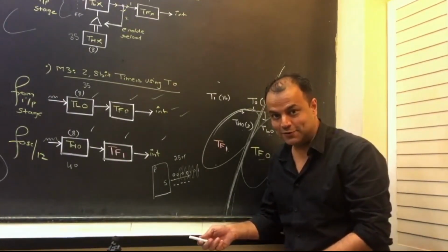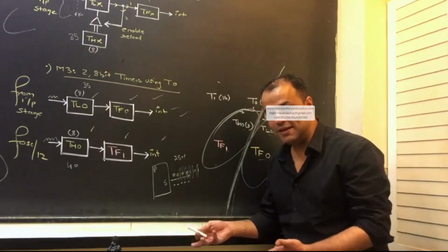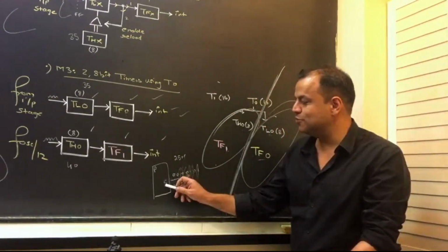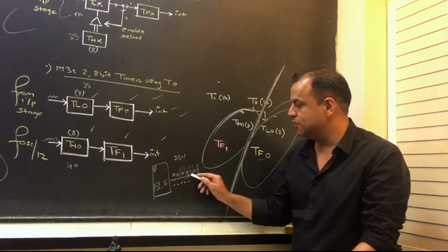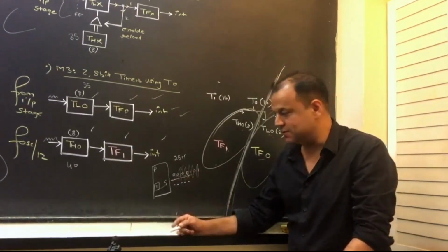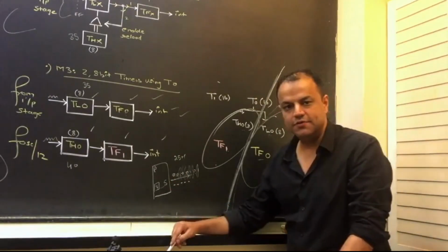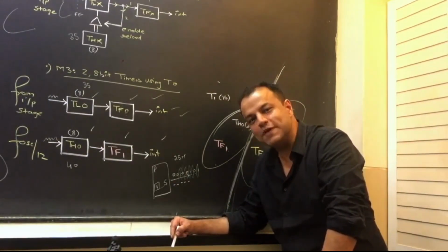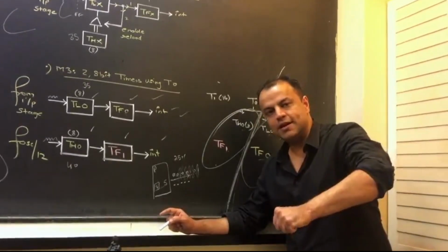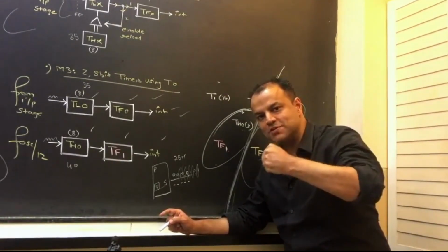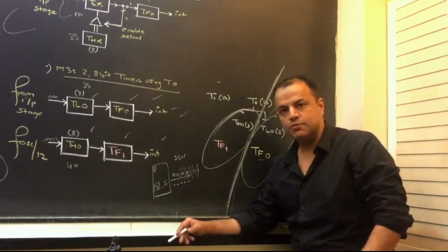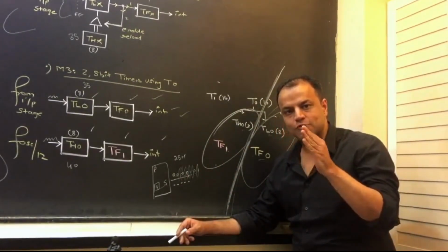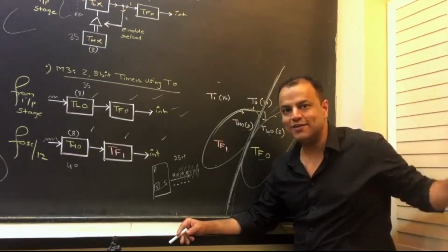We've been spending 1.5 hours on this. Please answer. Timers, delays are produced by timers. So what do you understand? When you do serial communication, you need a timer to produce the delay after every bit. The timer that is engaged in serial communication is timer 1. This is fixed. Serial port has internal connection with timer 1. Timer 1 is a personal timer of the serial port. That means whenever you do serial communication, timer 1 is lost because it is engaged in doing serial communication.